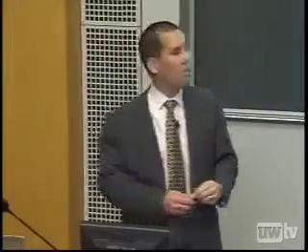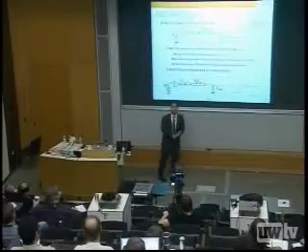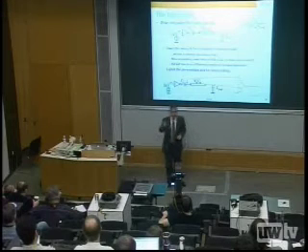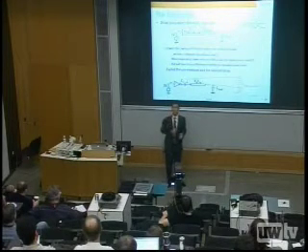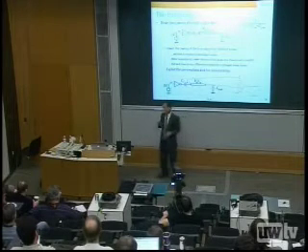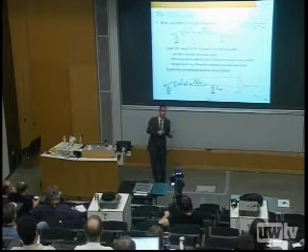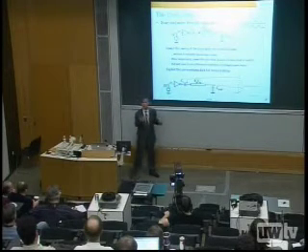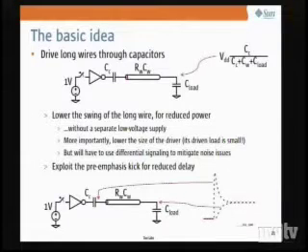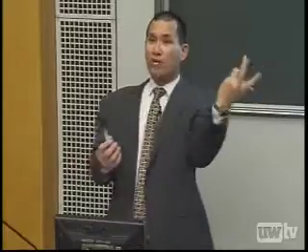That's low energy. And more importantly, I don't need a second power supply. If you do low swing signals on a chip and you want a 100 millivolt swing, you go to the power supply designers and ask, can you give me a 100 millivolt power supply? And by the way, I need the impedance of that supply to be 1 milliohm. You're not going to get anywhere because that's too expensive and a non-starter. So this lets me do low swing signaling without requiring a second power supply. More interestingly, with the series capacitor, the load that the inverter sees is significantly reduced. It's 1/10 the load it would have seen before, so the driver gets real small.